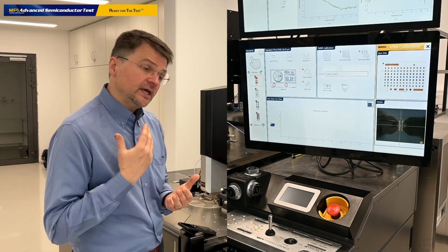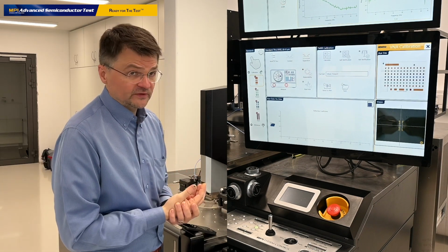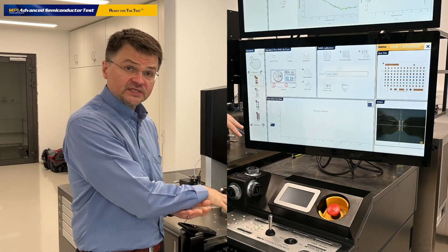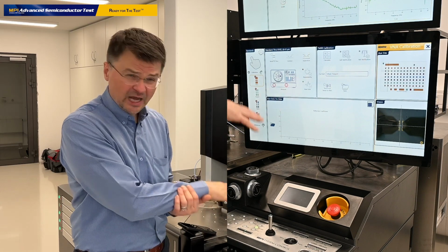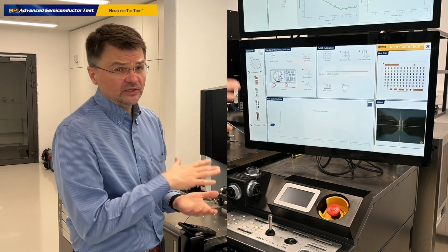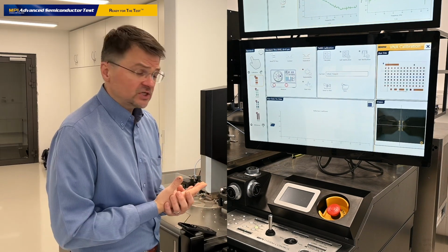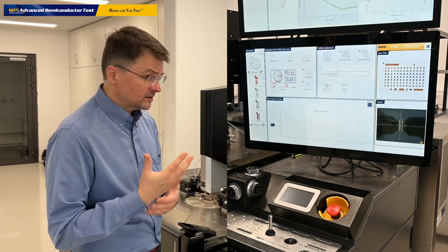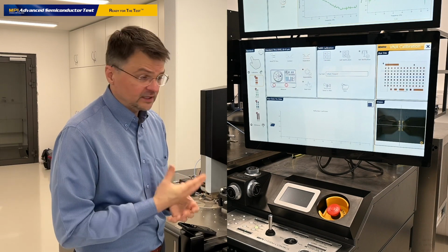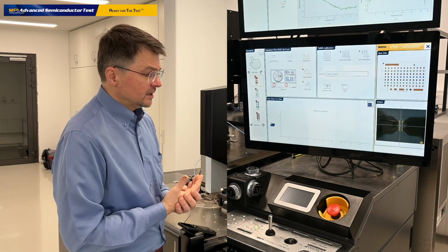How do we do it? It's a visual inspection of the quality of the calibration standard. I have a calibration substrate here on my system, which has been used a couple of times. Some of the standards are not in the best condition, so I would like to verify the quality of such a standard and select the ones which are better and which look more or less new.